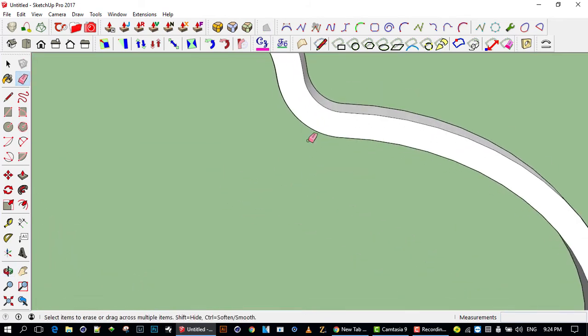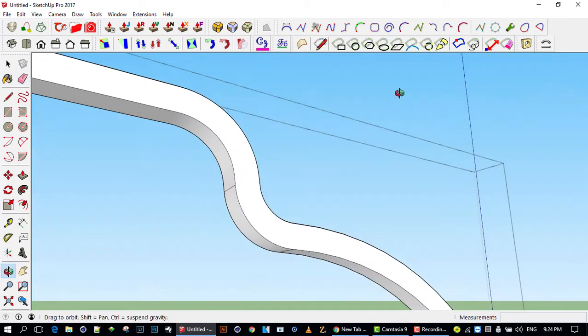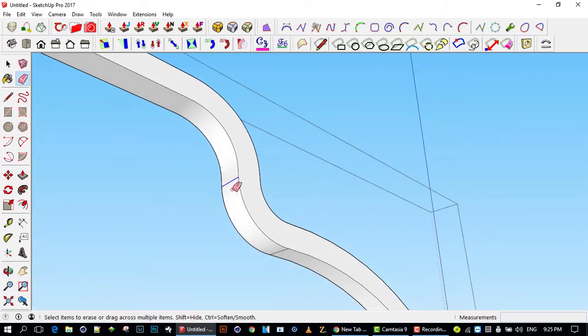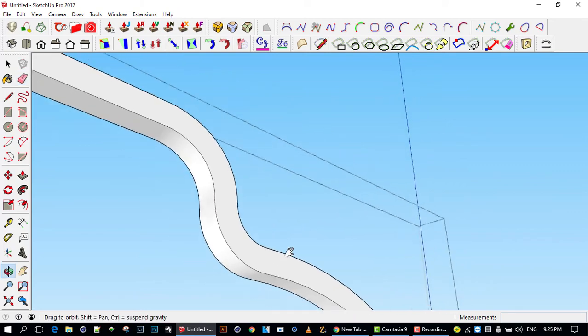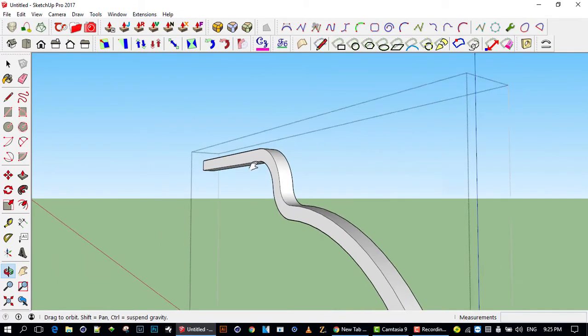In some cases you don't need to keep the shift button down and it will remove it, but in other cases, if you delete it, like I showed you there, I've just run the eraser over it, it cuts out that section. I'm going to go Control Z. So to just delete the edge there without making a hole in the thing, you keep the shift down and go over it, and it will just remove the visibility of these edges.